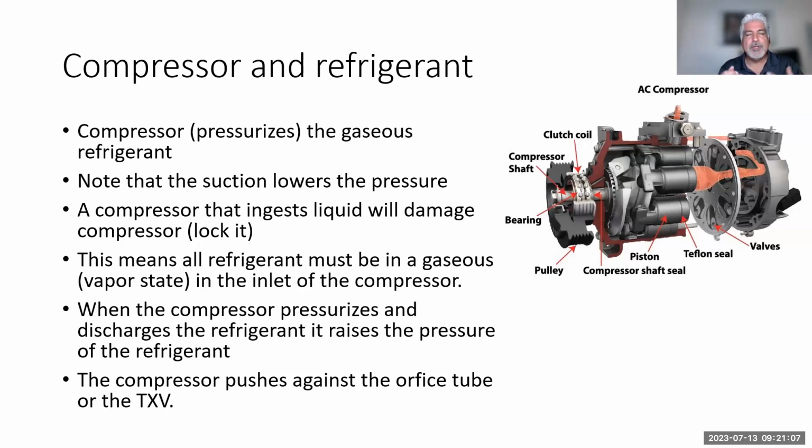The beauty of a variable displacement compressor was that it never cycled. You don't see the compressor kick in and kick out. Like my Toyota Tundra that I'm driving right now, that thing sucks. When you're accelerating, you can feel that compressor kick in and kick out. You literally feel it. While a variable displacement compressor will actually vary its displacement. It'll stay engaged, but it'll vary the stroke of each piston. It has the ability to do that using what we call a POA valve, meaning pilot operated absolute valve. So those to me are the best.